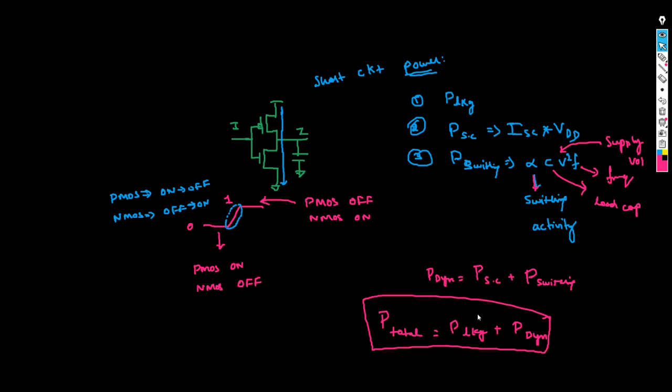So how do you optimize your dynamic power when you are implementing something for battery operated chips or devices? Dynamic power is also important. What are the different parameters that you consider? We try to bring the supply voltage down, and we try to increase the frequency. They are interlinked: when you increase the frequency, your power automatically goes up.